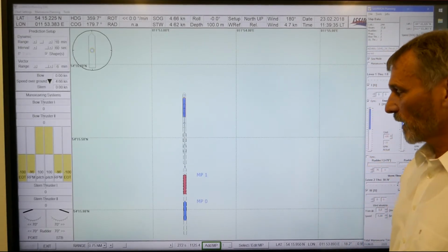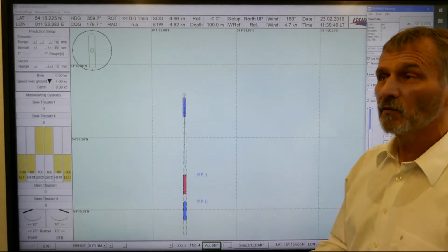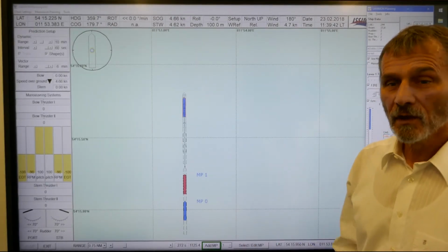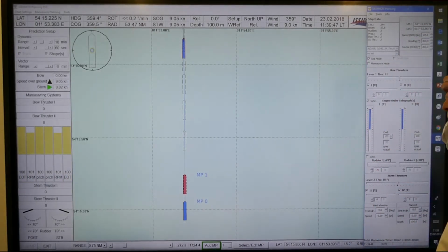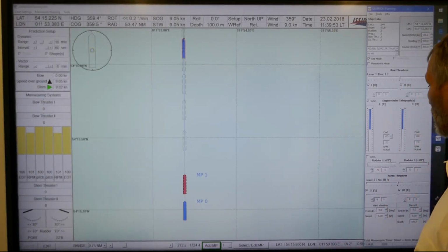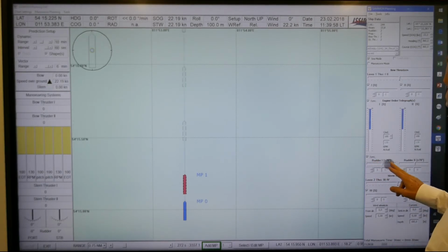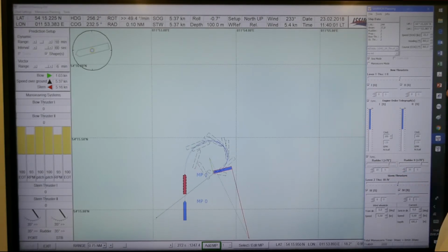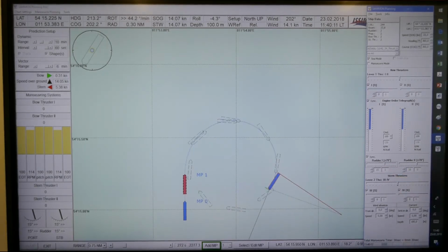What you also could do is, instead of stopping the ship, do another maneuver, maybe for man overboard. Instead of stopping the vessel, you go with full ahead. It's not suitable for a passenger vessel, but we will try it out with synchronized rudder to go maybe to 35 degrees. Oh, it's not good for a cruise liner because we go up to higher roll angles. So maybe we do the maneuvers with 15 degrees.